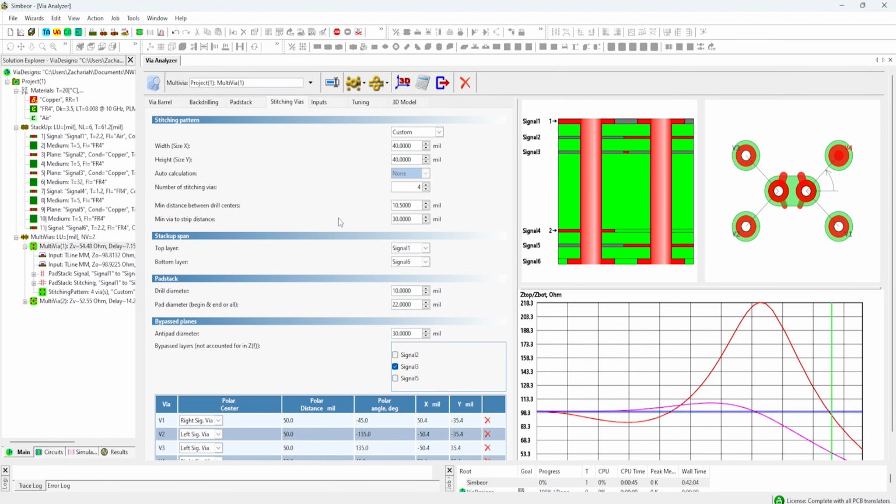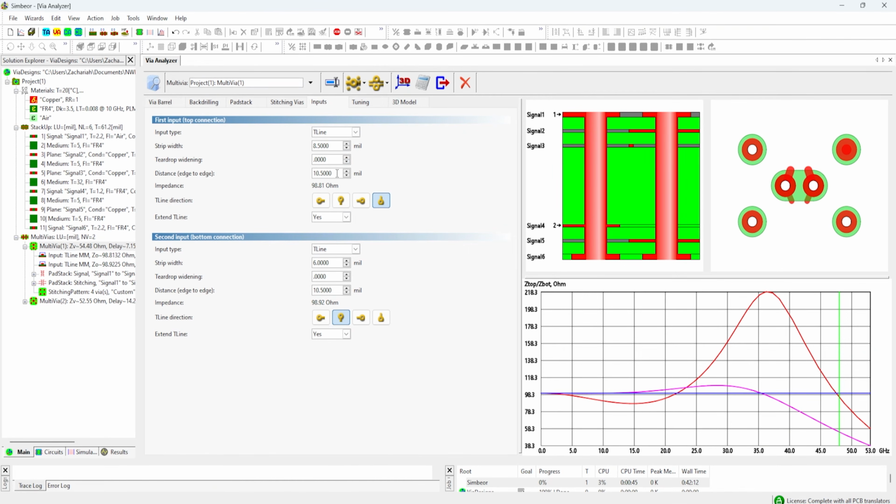Now, again, part of the reason for this is because we have this tight coupling between these vias in this stackup. So these 2 vias, again, separated by a pad-to-pad clearance of 10.5 mils, really dominate setting the localization frequency and the impedance in this differential via transition.